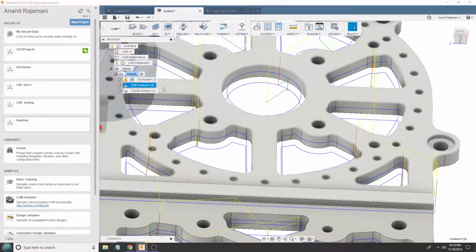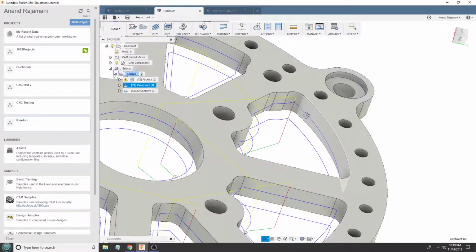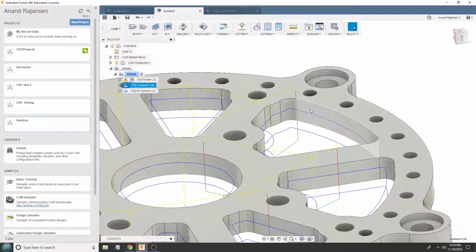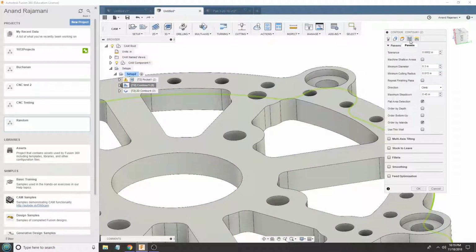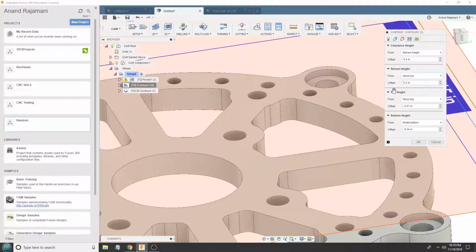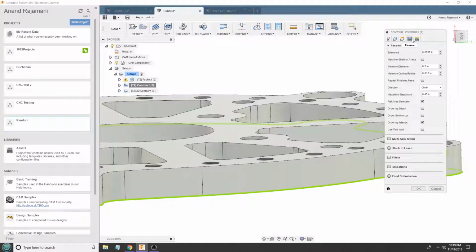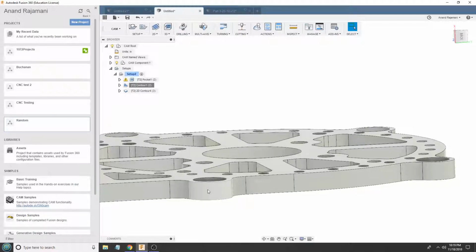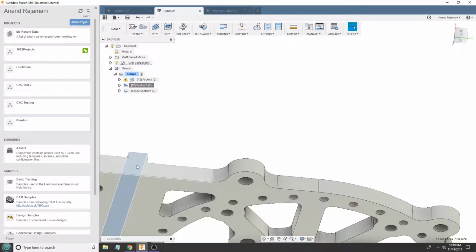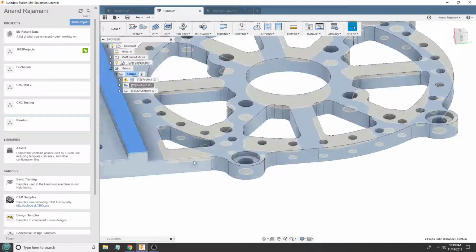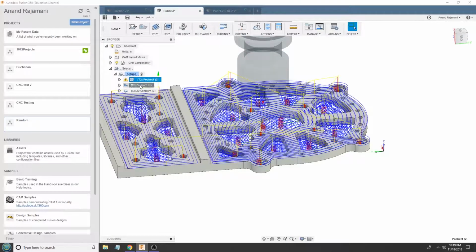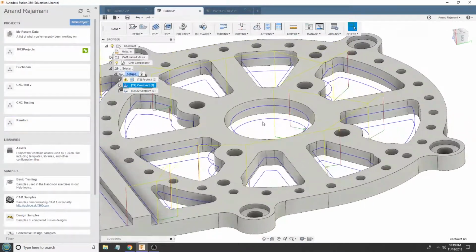It's so good. You can see here I am doing 2 contours. That's just because of the settings I have for this. I could probably force it to do 1 contour if I set the top height to be lower such that it lay below the top of here. But I don't really care. I'm totally fine with that not being a thing. Overall, this stock is 3/8 inch thick, so it's okay if I take 2 contours on this. It's not going to really make my finish suffer or anything like that.